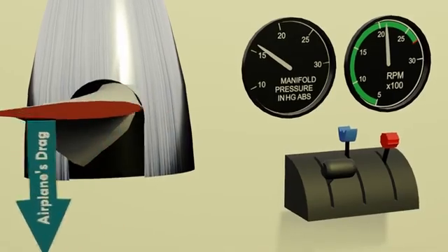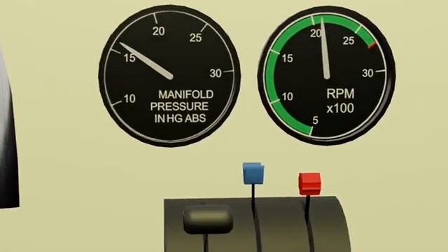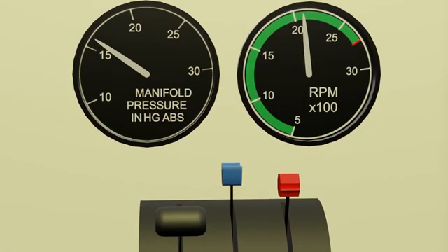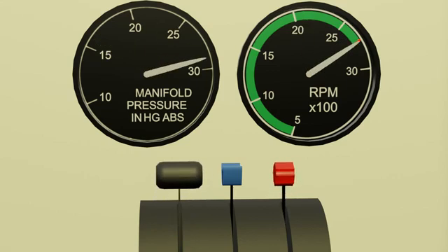What if you had to do a missed approach though? Power obviously needs to be increased, and now in the opposite direction from before. It's from right to left. Mixture, propeller, throttle, as if you were reining the power back in. This, again, discourages opportunities for detonation to occur.